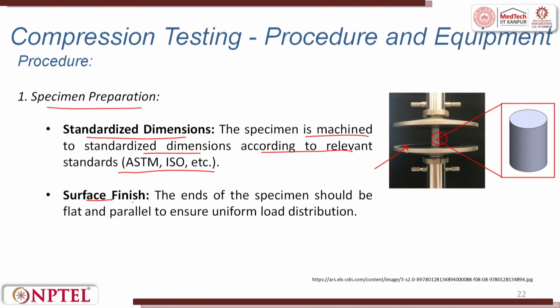Surface finish. The ends of the specimen should be flat and parallel to ensure uniform load distribution. This is to prevent premature failure.